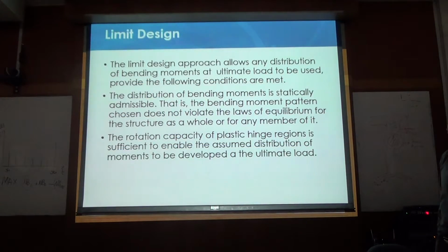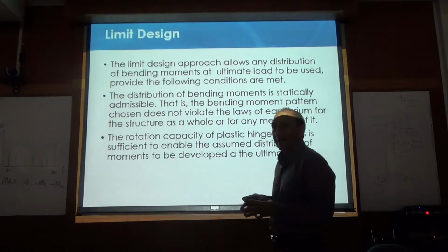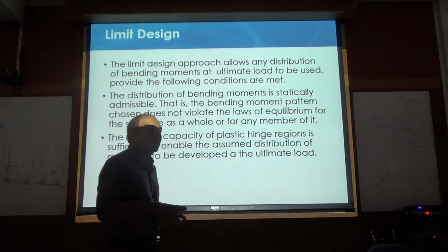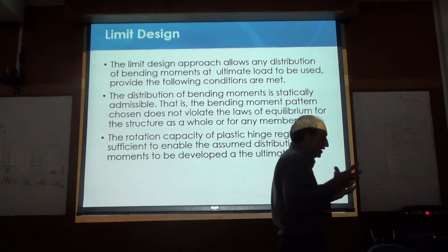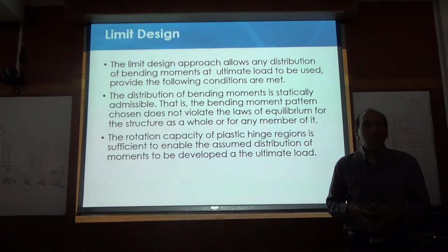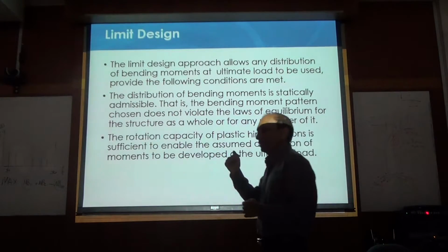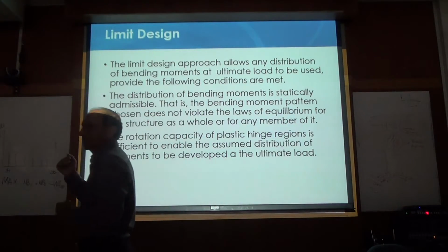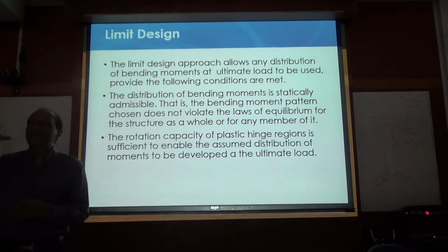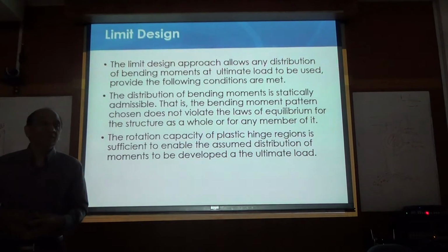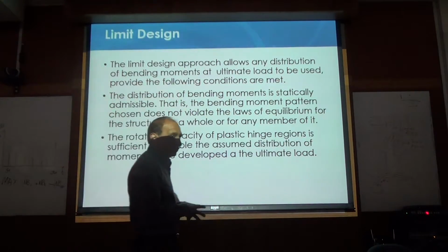So limit design means that you limit the moments at certain locations and allow the moments to jump to another location. So this is called limit design, or limiting design, or moment redistribution, or moment capacity-based design. You can call it many ways. The basic idea is that you allow the cross sections at some locations to have capacity less than what the demand is going to be. Allow them to yield, deform but not break, so that moment can go somewhere else, right? That is the whole idea behind this approach of moment redistribution.